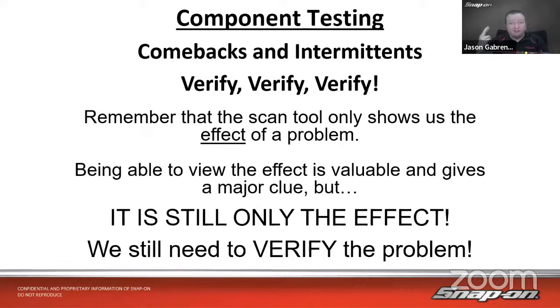Now, how about instead of crossing my fingers and hoping really hard that car doesn't come back, how about I test the part first? Test the part, verify that it has failed. If it has failed, I can be a lot more confident in ordering a new one. Then when the new one comes in, before that car leaves your site, test the new part.